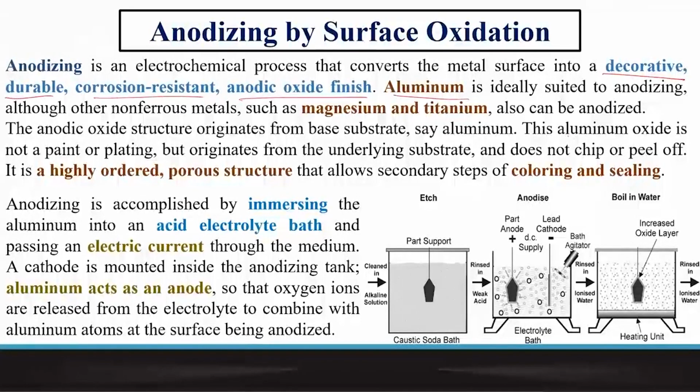And when it is used as an anode, it has a tendency of forming aluminum oxide on the surface, because as we all know, typically in an electrodeposition bath, the anode gets dissolved and deposits onto the cathode. So the cations move out of the anode and deposit onto the cathode. But the anions, when they are dissolved, if there is a certain concentration of anions present in the vicinity, then the released cations can react with the incoming anions and form an oxide or a compound layer. And that's exactly what's happening here.